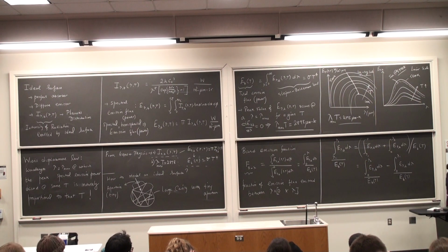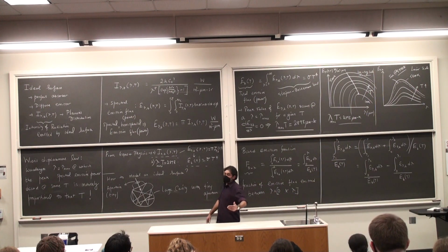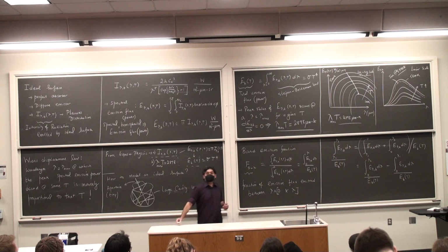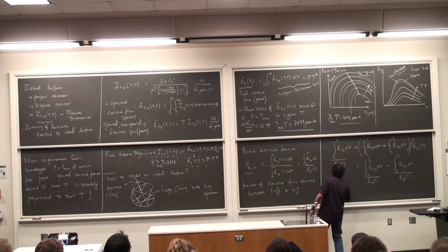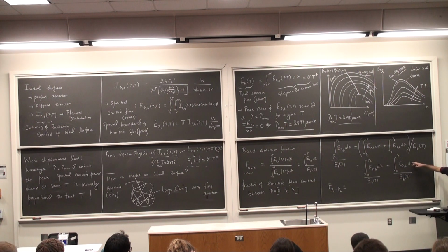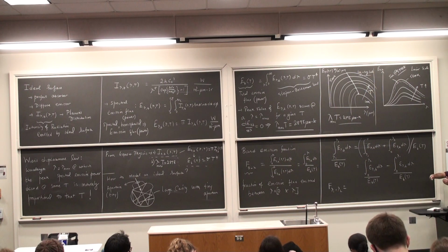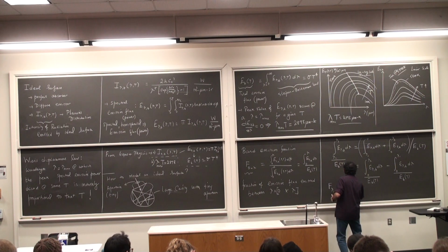And so I can say that the first expression on the left-hand side is the fraction from lambda 1 to lambda 2. So this is F from lambda 1 to lambda 2, which is equal to this fraction from 0 to lambda 2, minus this fraction from 0 to lambda 1. So from lambda 1 to lambda 2 I just take the subtraction of the two fractions.